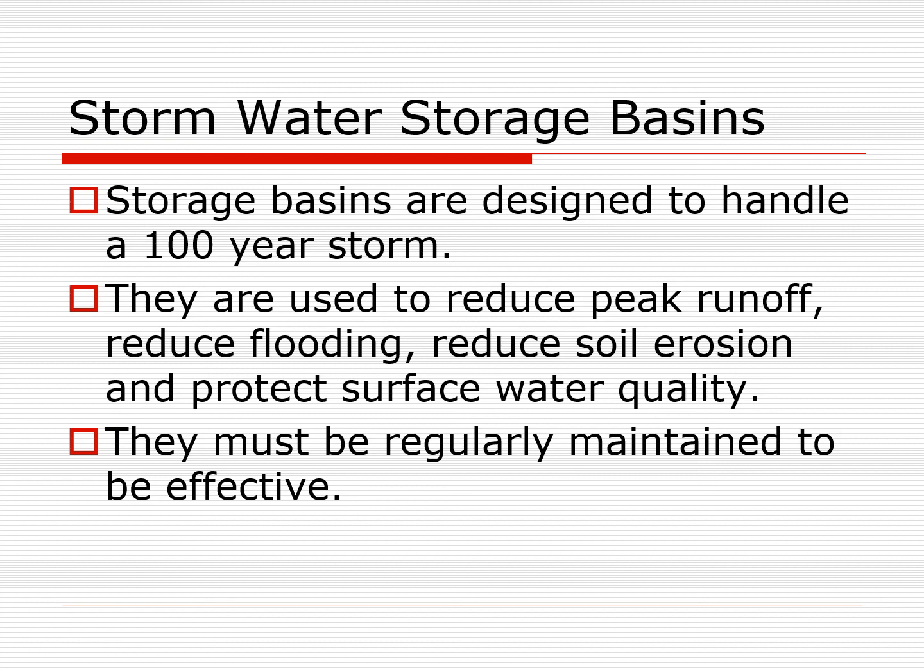So these basins, they're there to reduce the peak runoff, reduce flooding, reduce soil erosion, and protect the surface water quality. One of the ways they protect surface water quality is that if the water is sitting in this basin, the heavy stuff, so any dirt and particles that are in the water, will start to drop out into the bottom of the basin, so that the water that's discharged is cleaner water than what's in the basin.